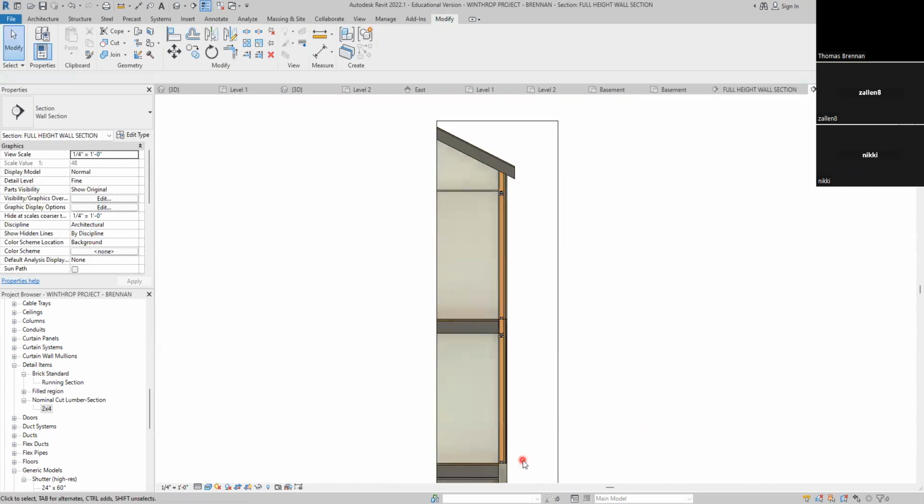Now we're putting that detail information in because Revit doesn't give that to us. Revit doesn't give that to us, so we have to supply it. This is where you're creating essentially a hybrid. You're using the section that's coming out of the Revit plan, but then you're adding additional detail because it's necessary on your construction documents. Because if someone comes out in the field and wants to build this wall and that's not there, they're not gonna know what to do. So because Revit doesn't supply that, we have to supply it. And this is how you do it.